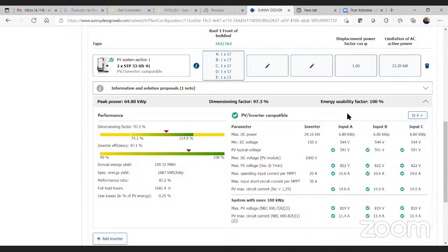So for the Core 1 right now, there is a device called the JMS-F. That is a 1-to-1, so a single module per single rapid shutdown receiver. There is a single module device from a company called AP Smart that is also certified for use with the Core 1. And there are 2 flavors of the dual module device from AP Smart, one rated at 15 amps input current per channel, and the other rated at 20 amps per input channel, kind of going back to these high current bifacial modules again, that are certified for use with the Core 1. So right now there are 4 devices that SMA would strongly say, if you're going to use SunSpec for shutdown, only use one of those 4 devices that is SMA approved for use with the Core 1. So again, a long-winded answer, but hopefully that relays that there are a lot of choices. There's also some interest in SMA in trying to comply with the rapid shutdown requirements inside of the array using UL 3741 listing. So we're trying to expand options for customers as fast as we can.